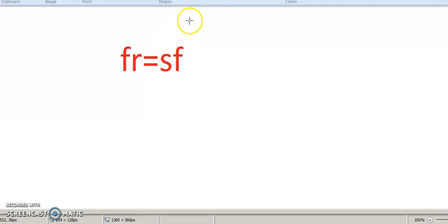Initially slip value is 1, but slowly it decreases to around 1 or 2%, or say 3%. 3% means it is 0.03 of the stator frequency. So Fr is 0.03 times stator frequency, which is 0.03 of 50 Hertz, so it will be very small. The rotor frequency will decrease.